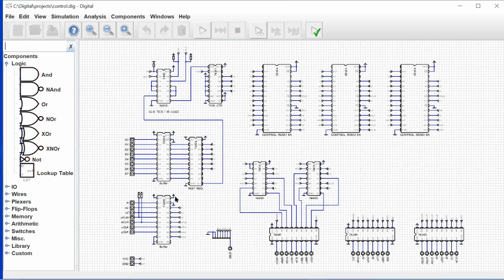The instruction register is really only used on this card, so it didn't seem like we needed to introduce essentially another bus into the physical design when we could just move the register. I also pulled the instruction step counter, or the tick counter, into the control card, because that's where it's needed.